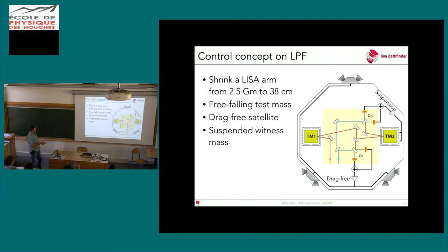And you can see that easily if you just change that angle to be 90 degrees. I don't have a picture of that, but if your test mass 1 is measuring here and test mass 2 is measuring here, it's very easy to see that you can translate your satellite to follow both in 2 degrees of freedom. And that's no different if it's 60 degrees. When it becomes different is when it goes to 0, right? Which is the case in LISA Pathfinder, you can no longer follow both of these test masses with one satellite. Eventually one of them will hit the walls.